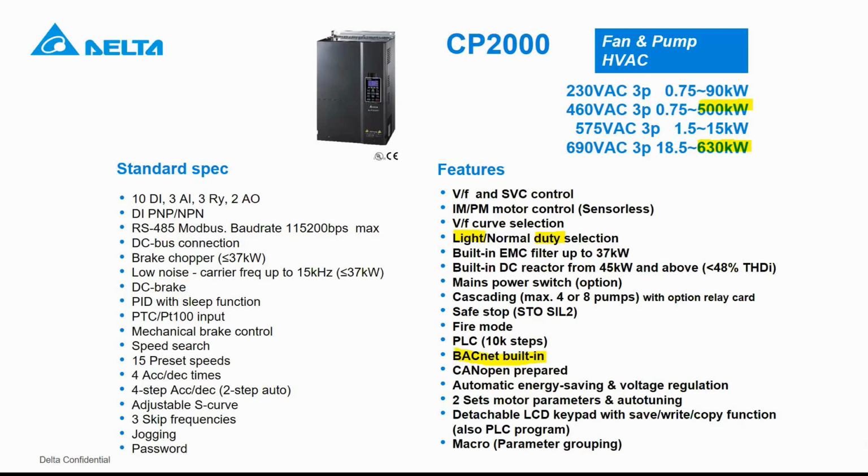And because it's made for variable torque applications, then of course you get some specific functions like cascading control, and multi-pump control, multi-motor control. And of course you get different functions for intelligent pump control.